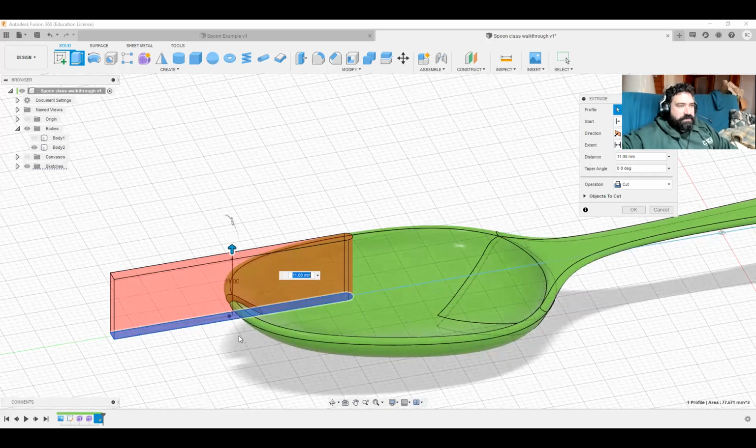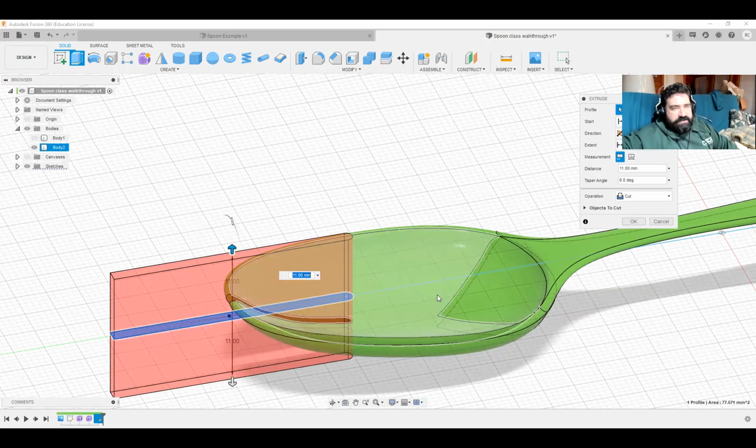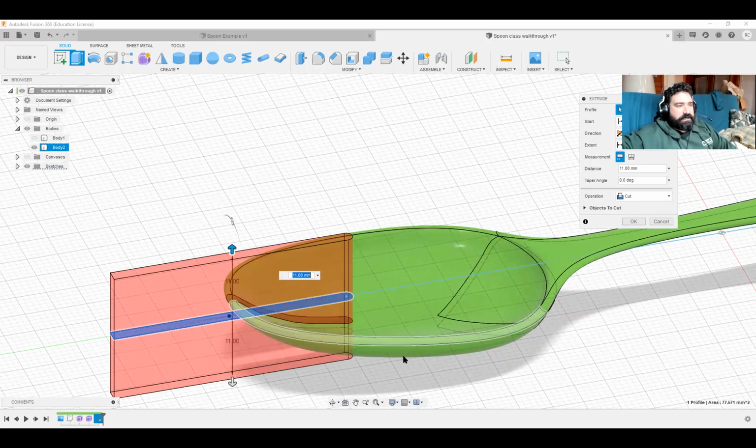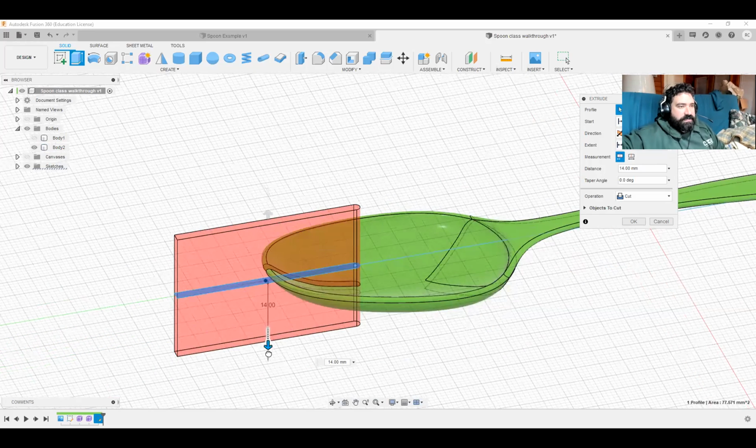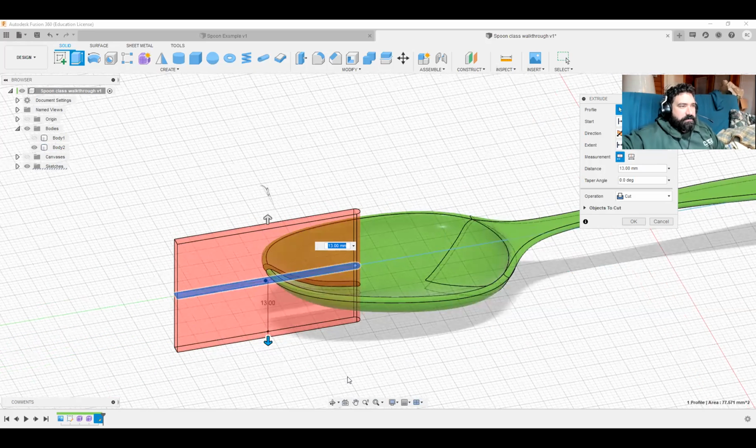So rather than doing 2 extrudes or anything like that, look at your toolbox, go to direction, not two-sided, but symmetric. Two-sided honestly would work fine also, but this just means that it's going to drag that extrusion up and down. And if I need to add more, there we are. But it's pulling it in both directions equally. And it's performing a cut function. Perfect. That's what I want.